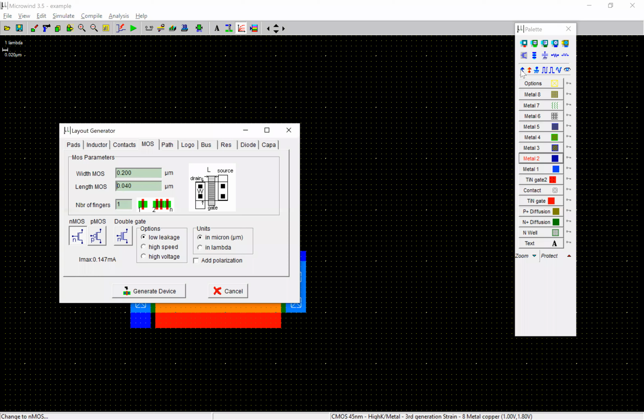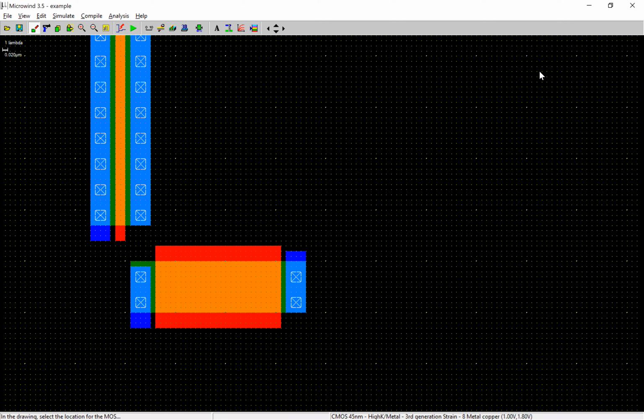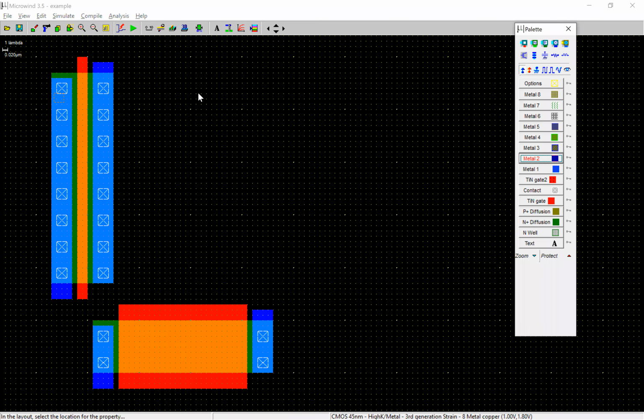Now I will just directly bias it. I take a VDD supply, and that'll go to one of the terminals on the left hand side of the top NMOS, and I'll ground the bottom NMOS right hand side terminal. So both are biased by this power supply. Then I take the clock, apply it to the gate of the first transistor, and make the same standard 1 nanosecond low and high.